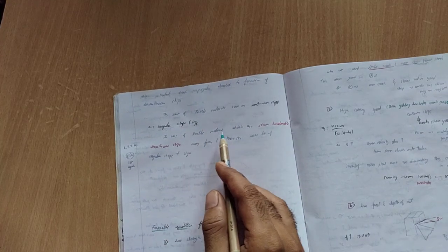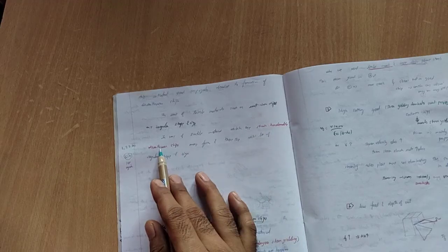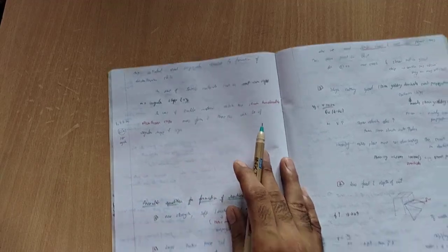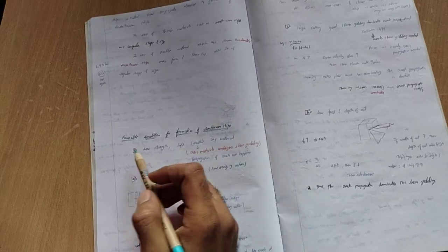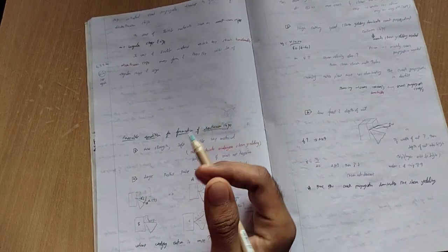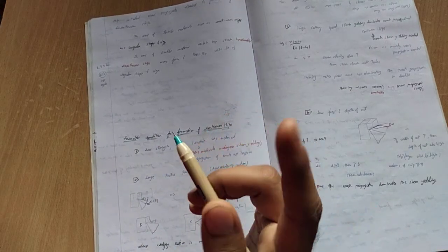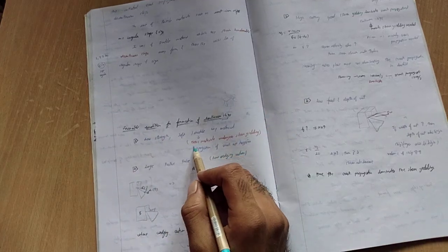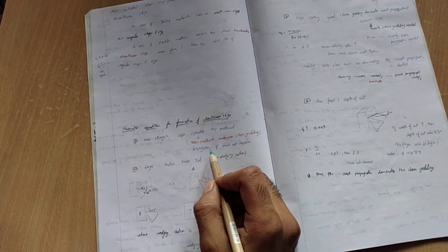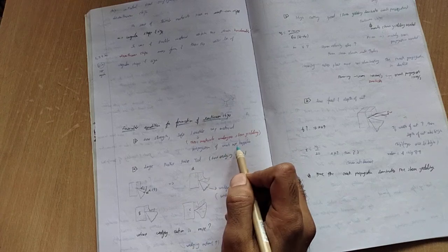In the case of ductile material where strain hardening occurs, discontinuous chips may form and the chips will be of regular size. Just a simple thing, no need to confuse yourself, just keep it in mind. So, favorable conditions for a continuous chip: a continuous chip definitely means the material should be ductile, low strength and soft. This material undergoes shear yielding, and propagation of the crack does not happen.